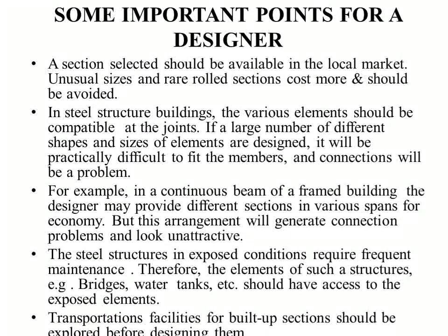So you must know that your designed section must be available in the local market. That is, unusual sizes must be avoided, and rarely rolled sections are also avoided because these rare rolled sections cost more.